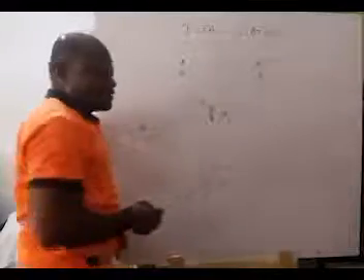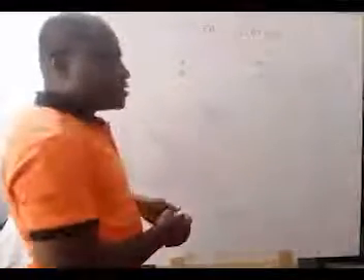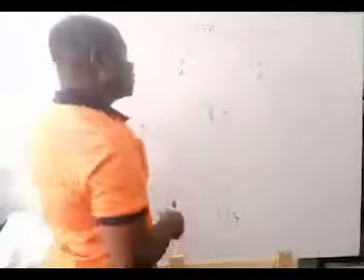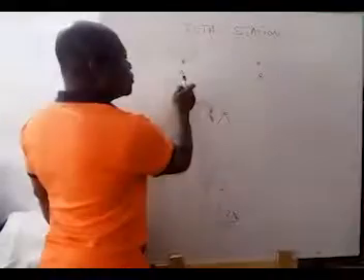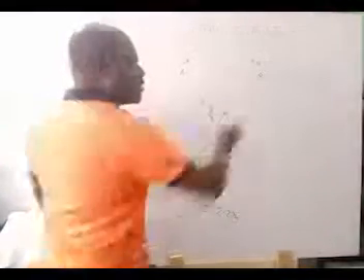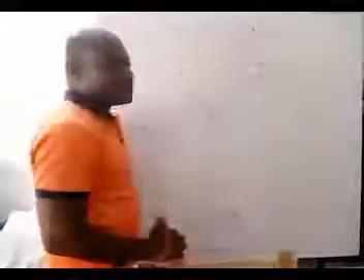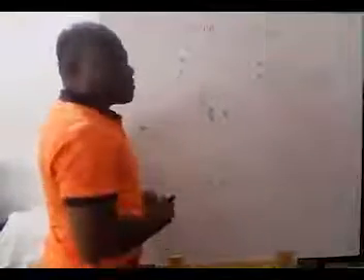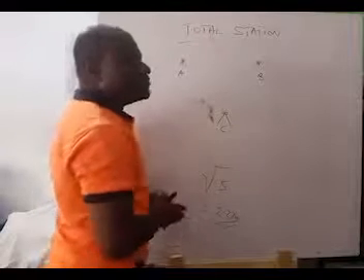That's X, Y. If you have the Z, you are working with heights too, so you add the Z coordinates. So you enter the coordinate for A, you enter the coordinate for B in the resection function in the total station. It will also ask you to observe to A, observe to B.